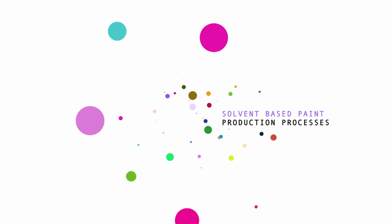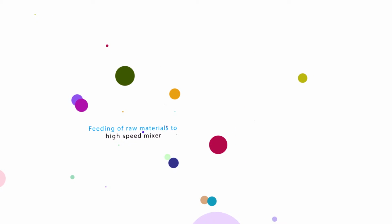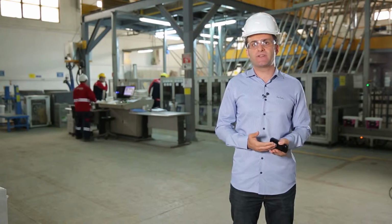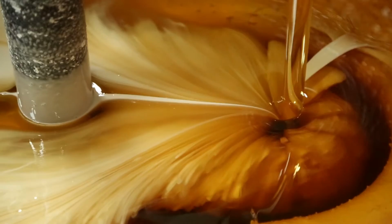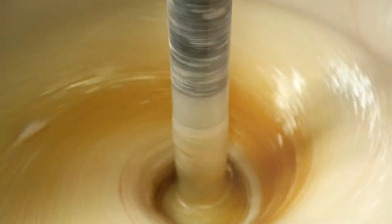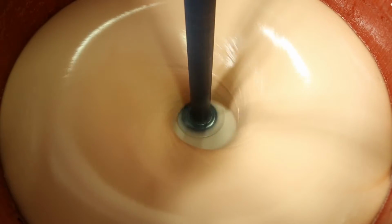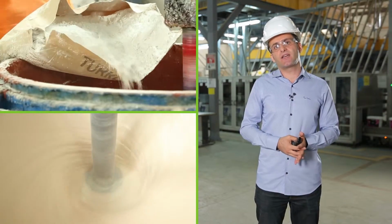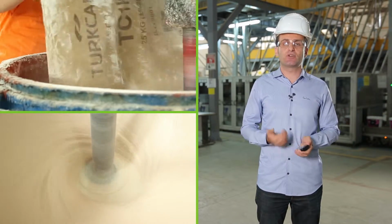Solvent-based paint production processes. Feeding of raw materials to high-speed mixer. In production of solvent-based paint, generally, alkyd, which functions as the binder of solvent-based paint, is added in the beginning. Then powder raw materials, filler materials and pigments are added before commencing the dispersion phase.